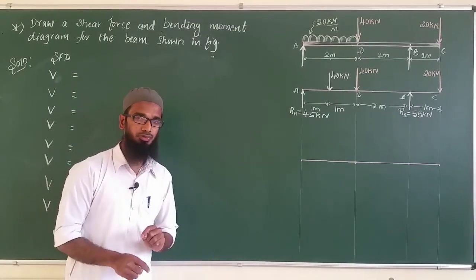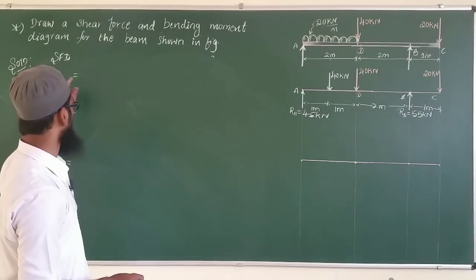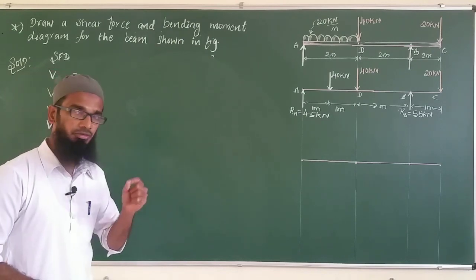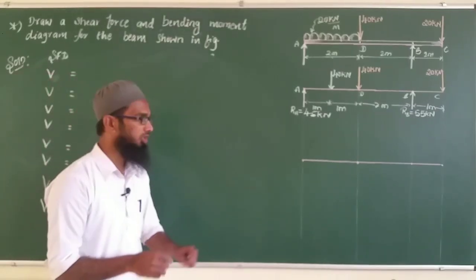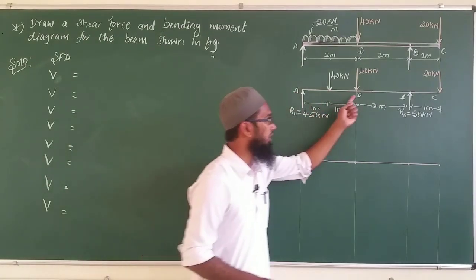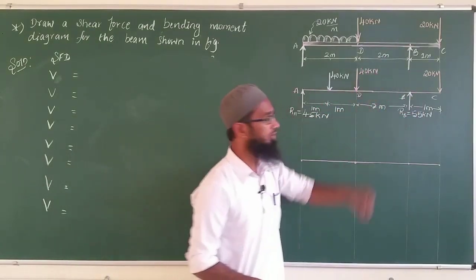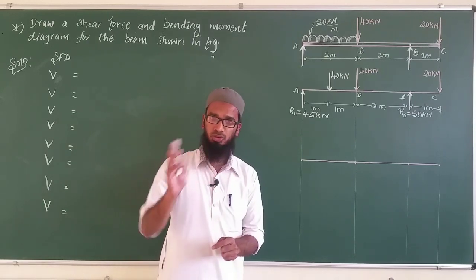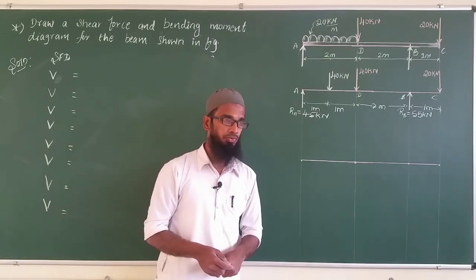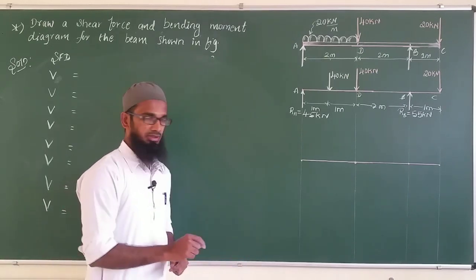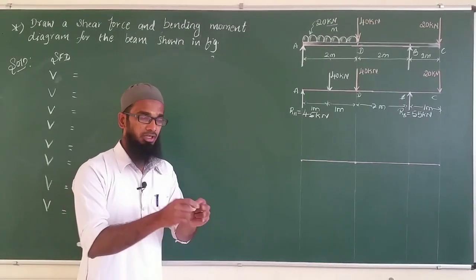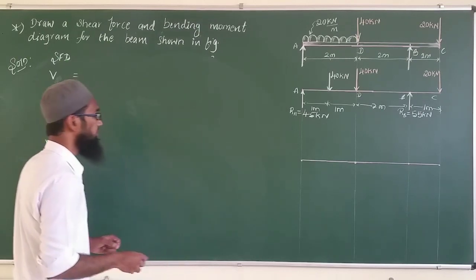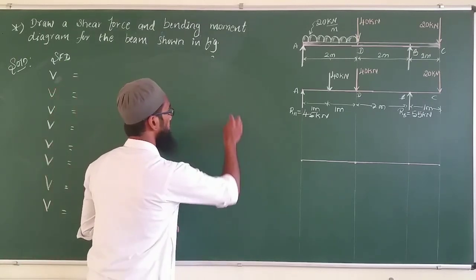To calculate the shear force here, I have represented the shear force diagram with V. Now I need to find out the shear force at every point like A, D, B and C, which is given in the beam element, by considering both the left side as well as the right side. To calculate this, we only have to consider the forces. After that I need to go for some sign convention. The very important thing is sign convention.